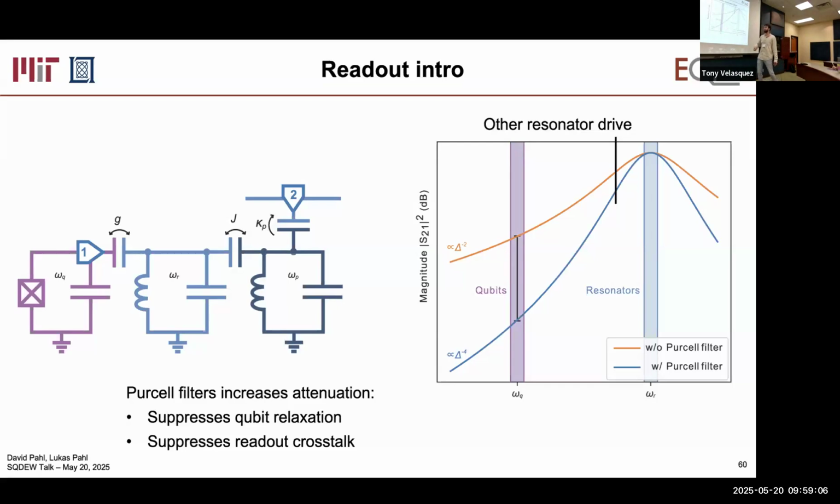The downside is your element becomes more complicated. This is a very simple way to do that. But how to do that is in Pozar. This is classical microwave engineering, just building filters with steep stop bands, Chebyshev filters, all your favorite filters. They're in that book, so you can just go read one and try to build it and connect it with a qubit.